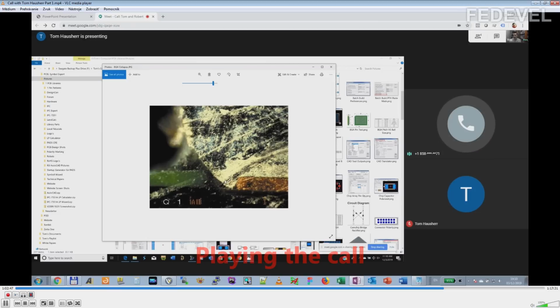But now the BGA pin pitch is getting smaller and smaller and smaller, okay? And then you get a BGA pad that's so small that if you collapse the ball around the pad, and you do a drop test, let's say you have a cellular phone or any kind of device that you hold in your hand and you drop it, the solder joint maintains its strength because the ball is collapsed around the pad, okay. But the problem is that the pad detaches from the board, from the pre-preg material. So when you drop a handheld device and you open it up to see why it failed, it was the pad that ripped away from the pre-preg. The blunt force, yeah, because they are so small that the weakest point is actually between the copper and the pre-preg. Right.